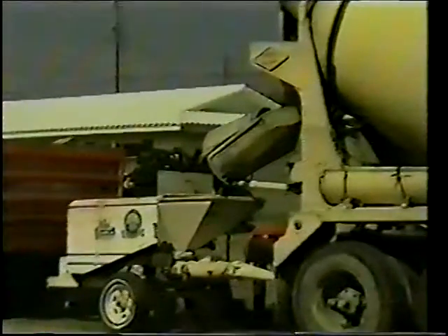Sometimes flowable fill is used in place of compacted soil. Flowable fill is a mixture of soil, water, and cement, and sometimes fly ash or additives. In pipeline construction, it can be used as the embedment, the backfill, or both. For both rigid and flexible pipe, flowable fill is placed to the same level as for compacted soil. Care is needed to prevent flotation or misalignment of the pipe.